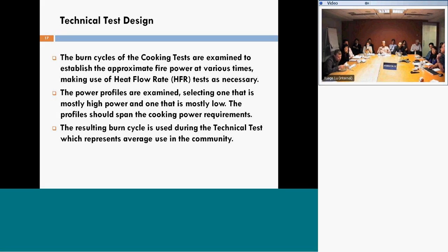The heat flow rate is the heat going into the pot per square centimeter. This may apply to any pot size. So do not report cook power in watts, because if you have a bigger pot and a bigger stove, that number is relevant. Heat per square centimeter tends to be quite constant. So across a range of pots, places, people, and stoves, we find that the heat flow rate that women consider acceptable performance is 2.7 watts per square centimeter in Central Java. It differs in Sumba. They want 3.5 to 4. They want huge fires. They want 25 liters of water to boil now. And that's cultural preference, and if you bring something that's 1.8, they will not accept it.